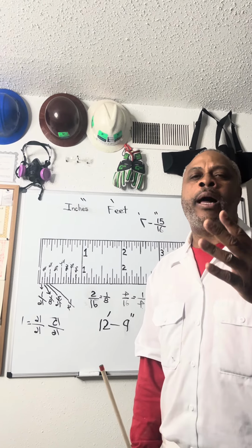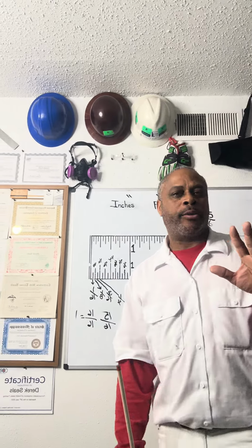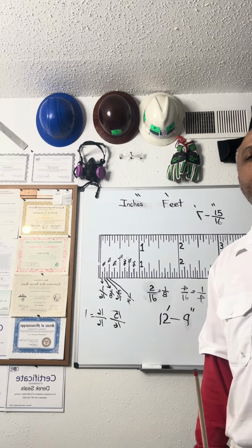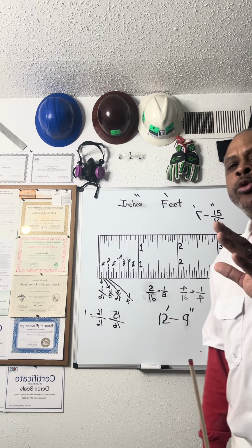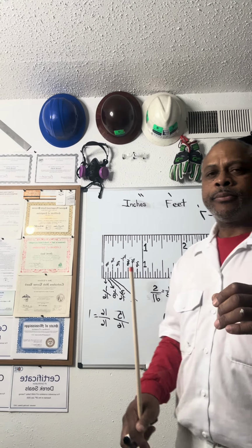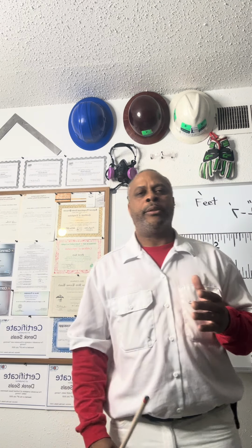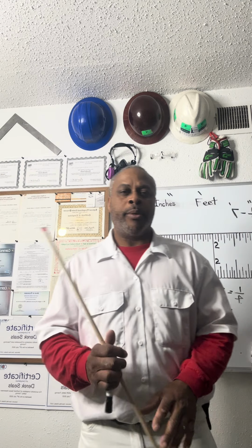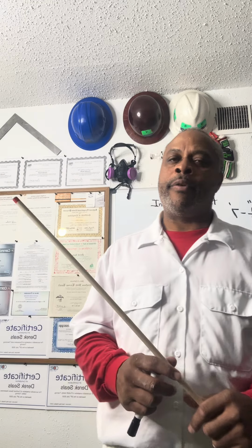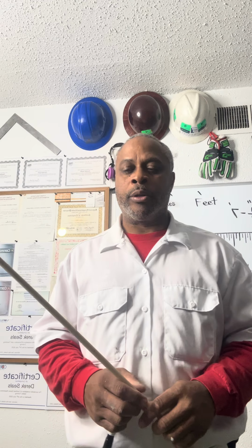Now remember, plywood is usually 5 layers, okay? If you go through the membrane of the plywood and overshoot it, there's going to be a problem from the inspector, okay? A very, very serious problem from the inspector.